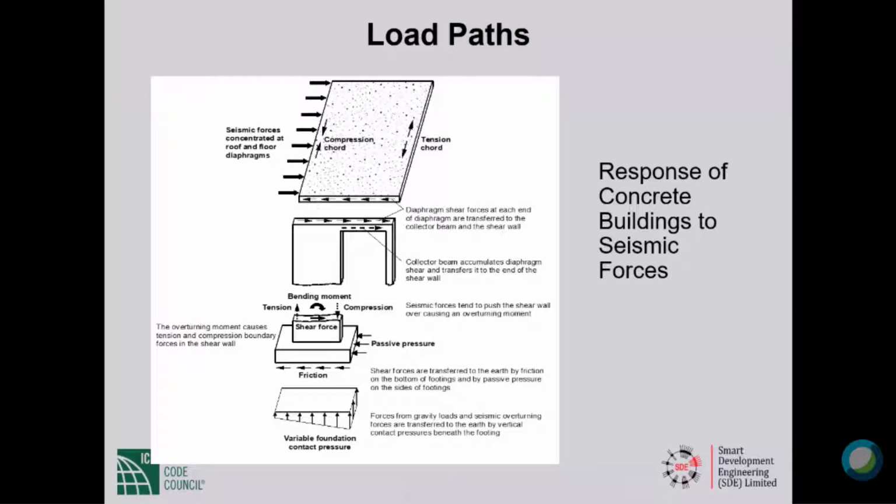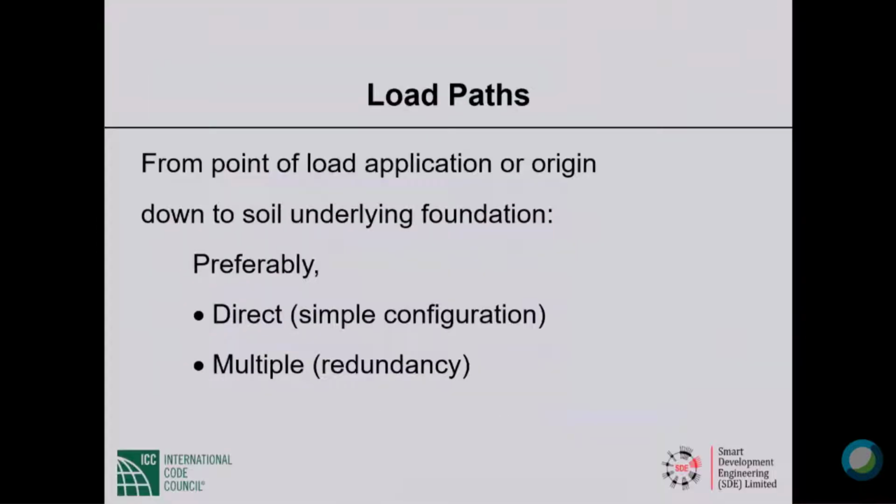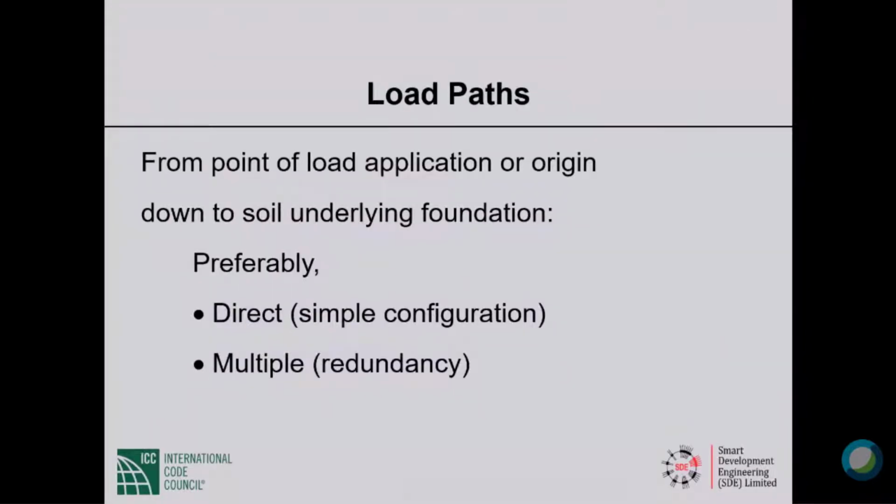So earthquake engineering, in its essence, consists of taking the inertia forces from where they originate, namely the floor and the roof diaphragms, down to the ground underneath the foundation where all forces belong. So we have to provide load paths from the point of load application or origin down to the soil underlying the foundation. This is what the engineer has to do.